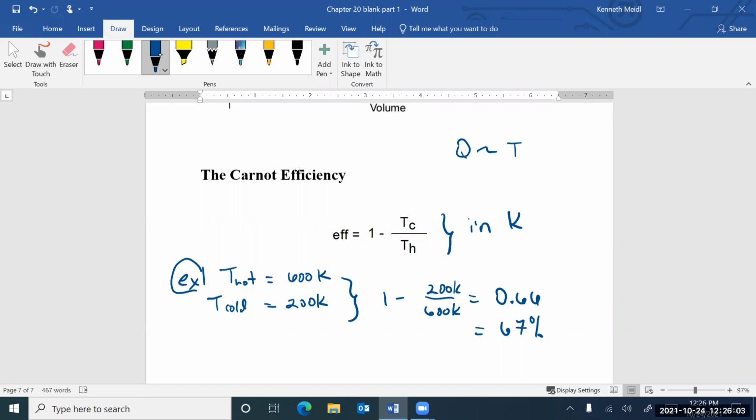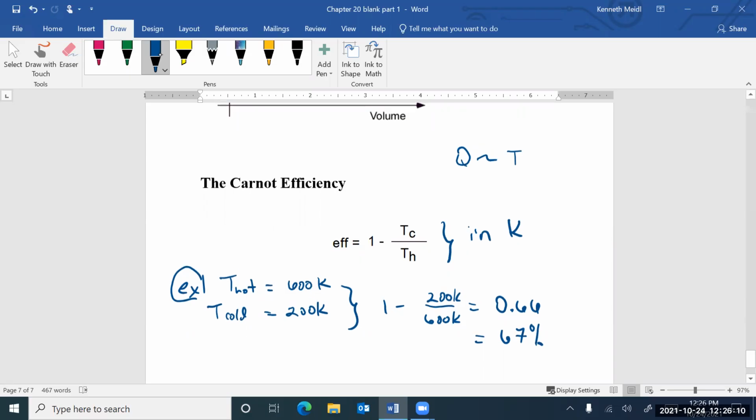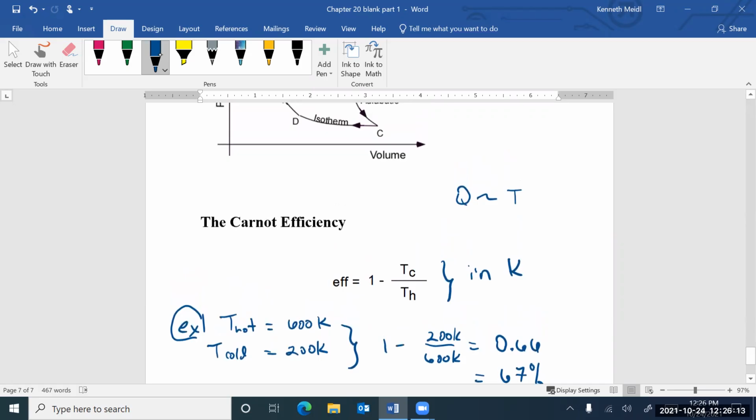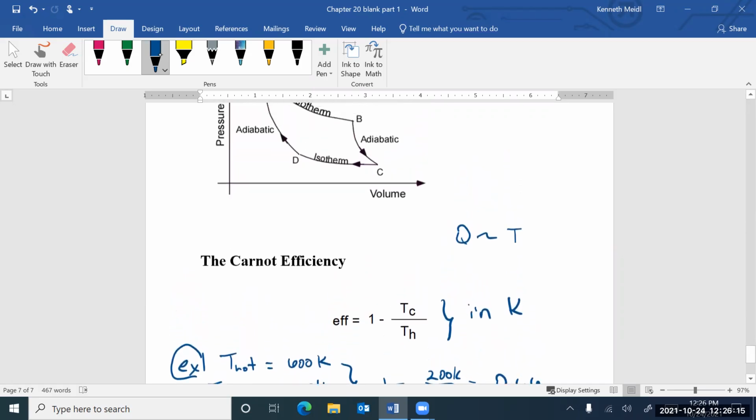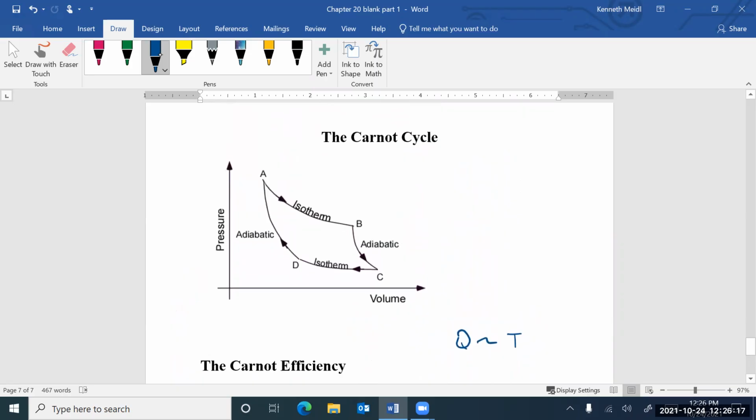Very, very interesting. Easy to deal with here, but what I would take away is this definition of the Carnot efficiency, knowing what that really means and entails, and then the Carnot cycle, right? This is really your theoretical best cycle between your hot and your cold. Once you have determined how hot you can get your gas and what the exhaust is going to be, this is the cycle that you want to have working for you, or something very close to that.